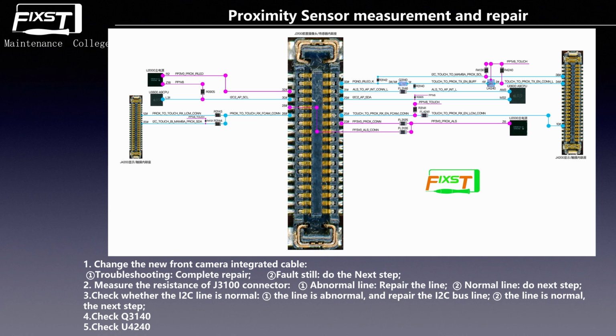Actually, the screen can work, it means that the LED line is working. The LED needs to work, we just give the power to it and it is okay. So we see the power point. You find the pin 1, pin 3 and pin 5, these three pins. These three lines are the LED power lines.